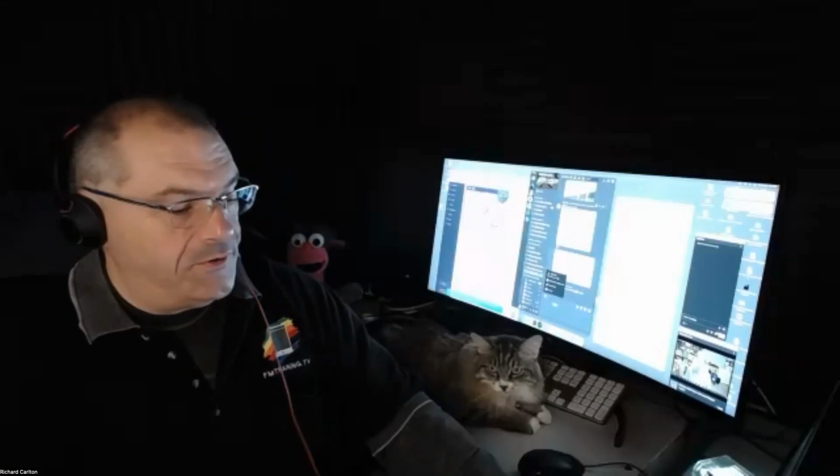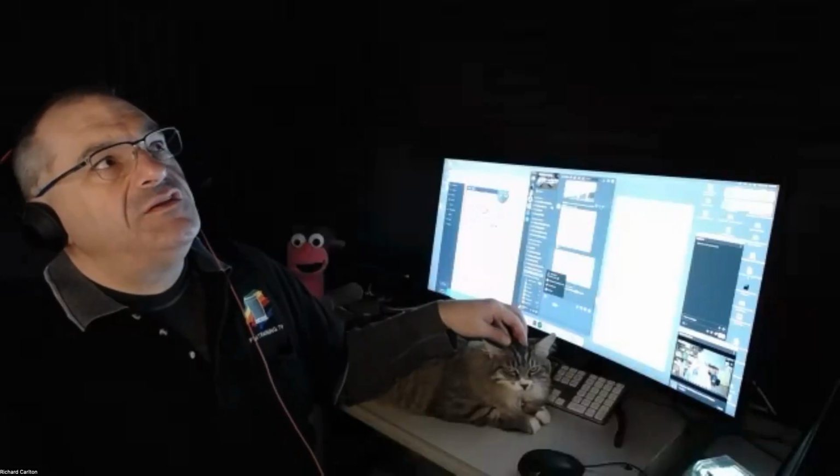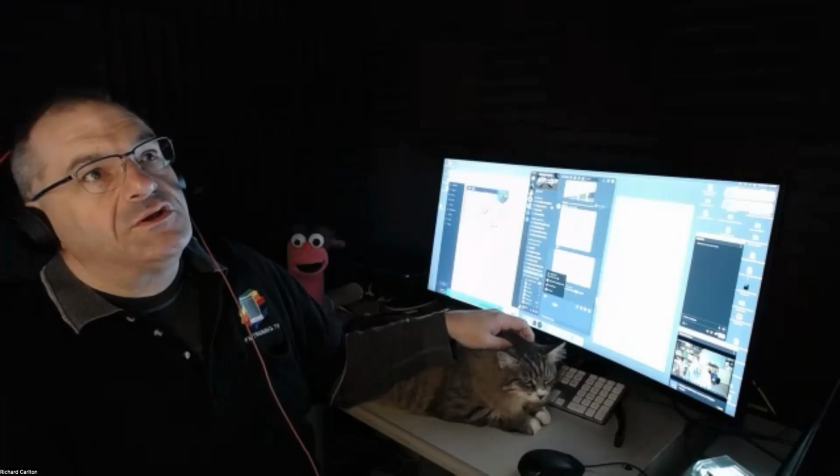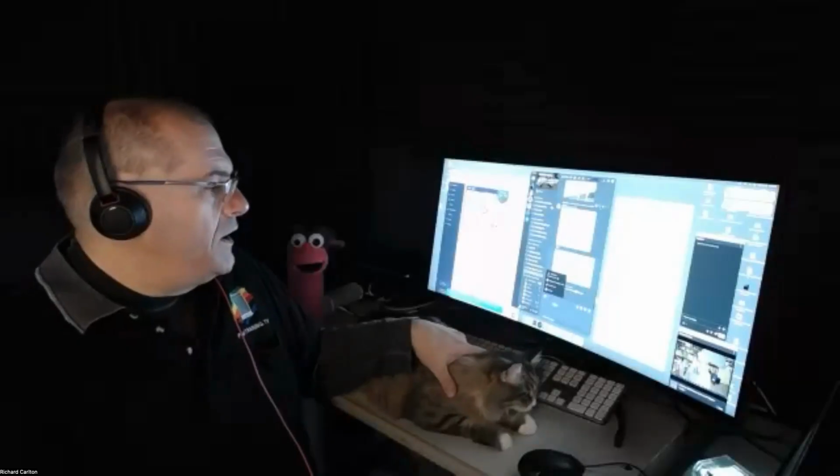The distance sensor, we came to the idea that sometimes people need to automatically take pictures of things held in front of a camera, so the distance sensor could detect if there is something. Then here I got an infrared receiver. So if you have a remote control, you could turn things on and off. I've never looked at what those signals look like digitally. Basically, we can test it later. It's just 3 hex numbers or so per key. So in the script you would get the hex number and then decide which action to do.